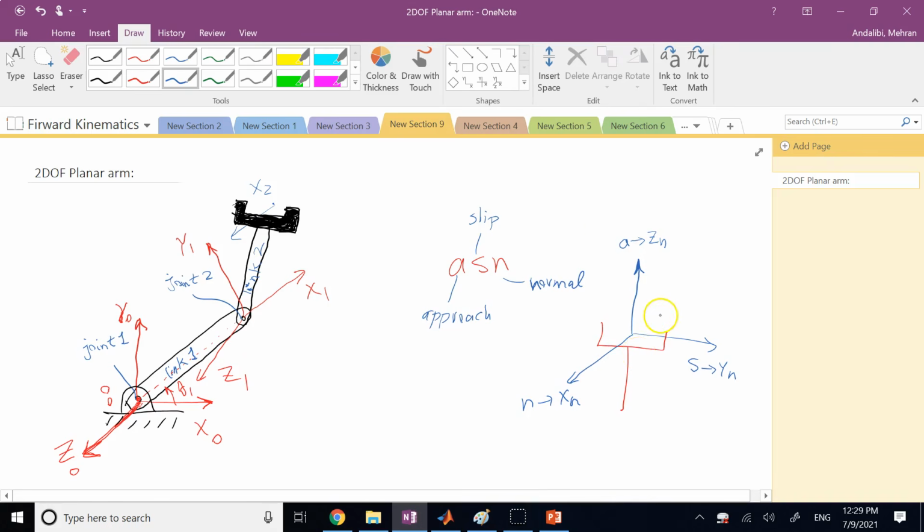So if I want to use it, instead of setting my A to be the z-axis, I have to change it. And I have to choose my A to be the x-axis, actually. Because that's the only solution here you can have to keep the DH convention working, the assumptions not violated. Because remember, my x2 has to be perpendicular to z1. z1 is out of the plane, so my x2 has to be in the plane for sure. And then it has to intersect z1. And the only way that it can intersect z1 is, again, what? It is along the direction of link number 2. So that's the only solution here, so that when you extend it, it intersects z1. So in our case, we have to say the approach direction is xn.